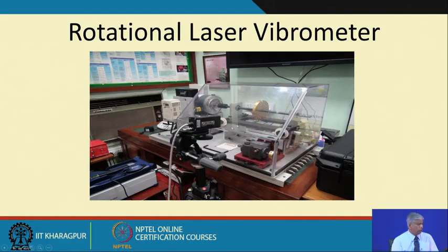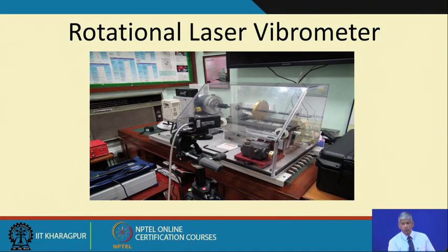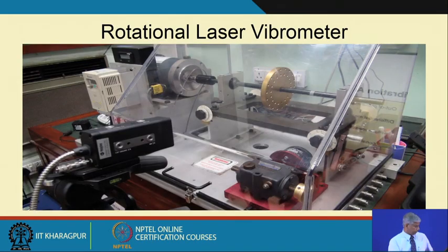This is another view of the rotational laser vibrometer. And these systems are very expensive compared to the traditional linear based vibration measurements using accelerometers or optical encoders. Nevertheless, they are advantageous because they are non-contacting and you can measure them from a distance.